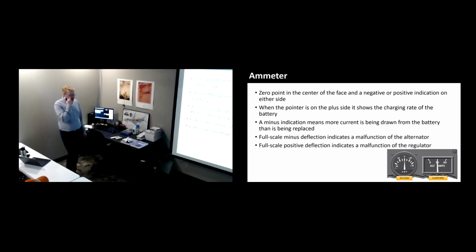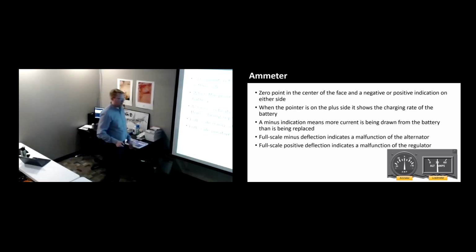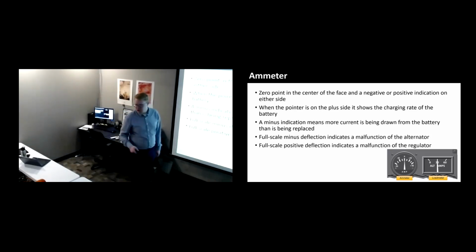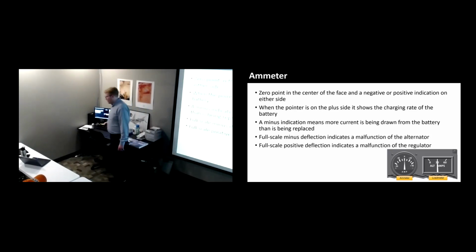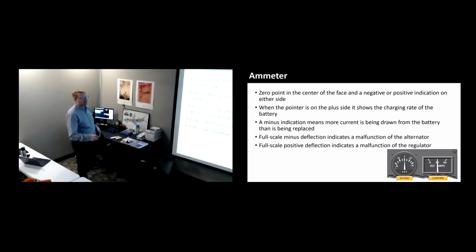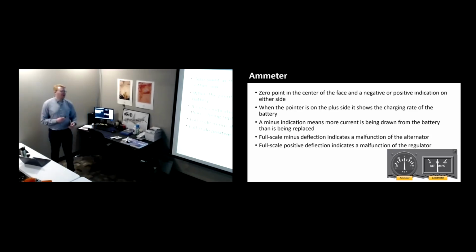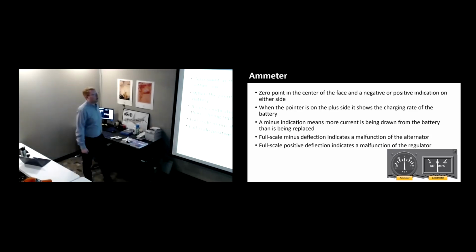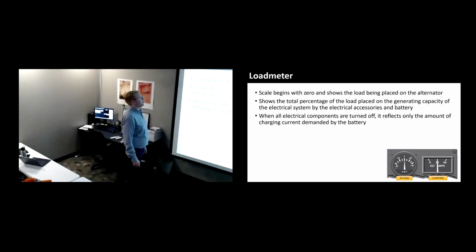Yeah, so in airplanes that are equipped with a load meter, they're usually simultaneously equipped with an ammeter or a digital display. Most cockpits, if the alternator output falls down to 0, it'll give you an indication in the cockpit. Usually a little ALT light will come on or something that indicates alternator failure. That'll be your sign the alternator stopped working. If the aircraft's equipped with an ammeter, you'll see it there as well. A load meter is really not necessarily designed to show you whether the alternator is working, but to show total system power. So you'll have other indications of that through other sources.